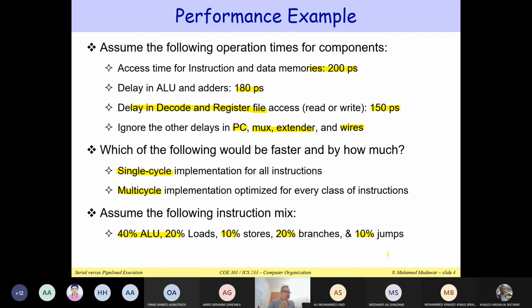So you need a register for the instruction. After the instruction memory, this is where you place the instruction. You need maybe registers at the inputs of the ALU, after you have read from the register file and before you execute. After you execute, you need a register after the ALU. After you load the data from the data memory, you also need a register to put the data. And then finally, you can write back the result into the register file.